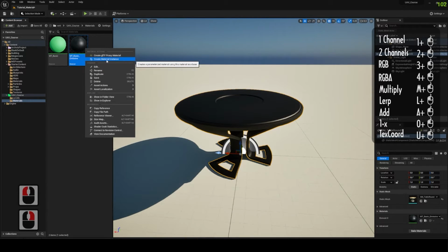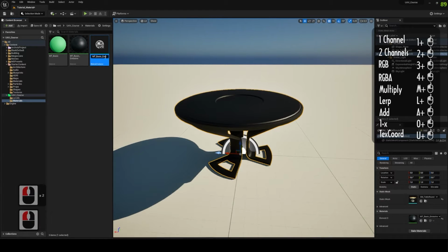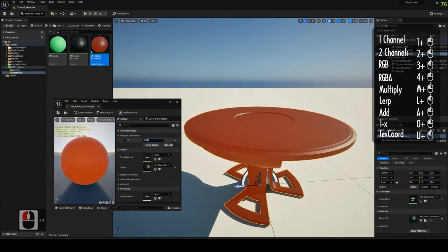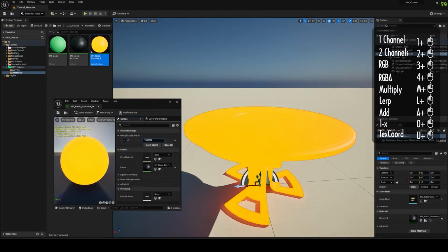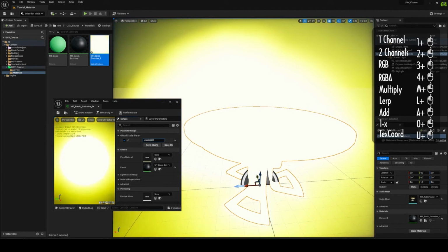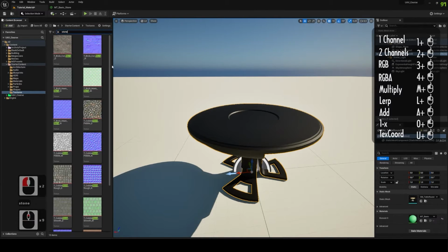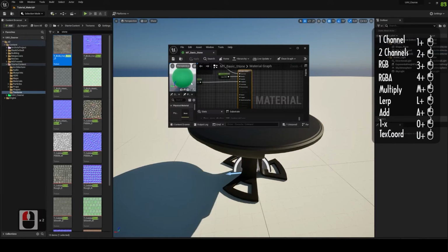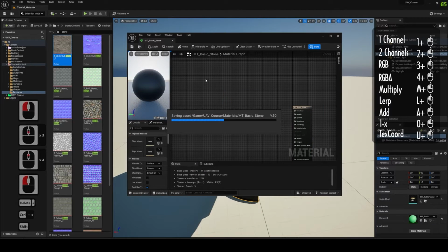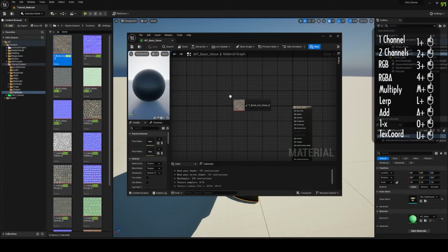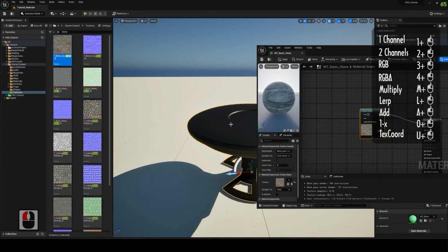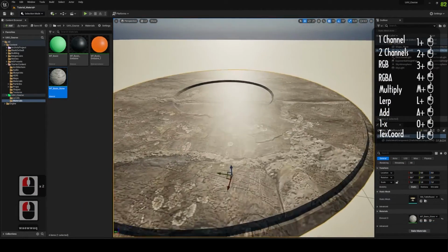To be able to control this in real time, we right-click on the material and select Create Material Instance. The parameters we create from this copy become easily controllable, and we will use this feature a lot. Now that we have learned the basics, we can start using textures instead of our base color. Our starter content contains many stone textures. When we transfer the stone texture to the material blueprint and connect it to the base color, you will notice that there are no details.